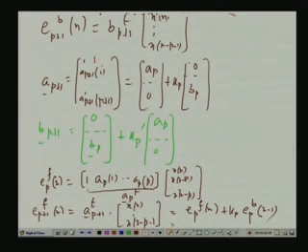So what you get is what we have seen already: first is EpBn minus 1, and second term, that is Kp prime, another vector is Ap, 0 transpose. We have already done it in the previous case. The 0 is the last term, forget the last term. Ap transpose times a vector that starts at xn and goes up to xn minus p. So Ap transpose times that vector is once again EpFn.